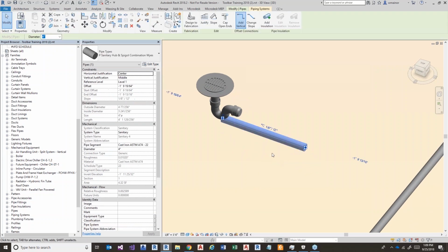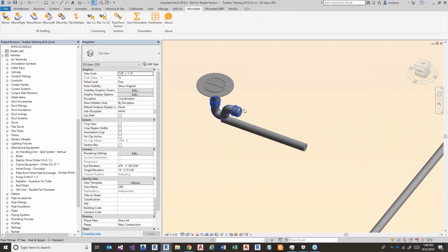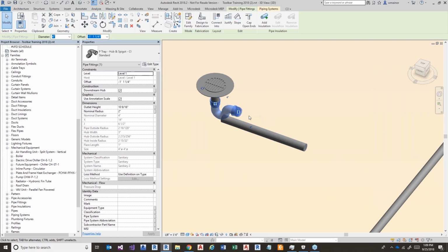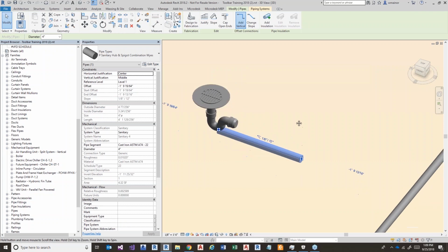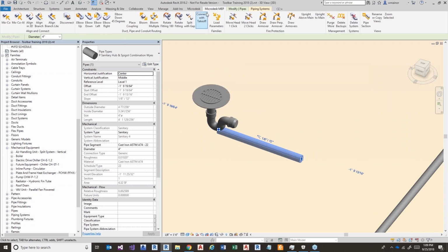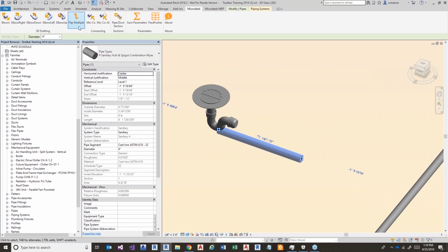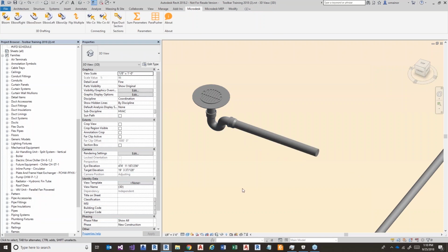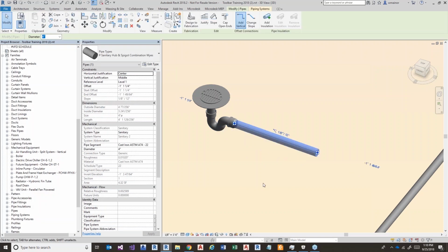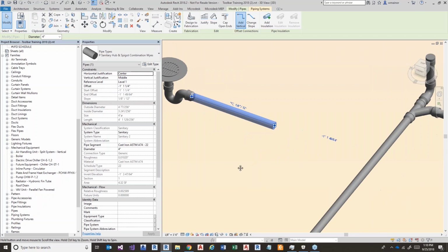And now, I wouldn't want to use the move, connect, align on the P-trap because this connection doesn't have a slope associated to it. But my branch line does. So we've got another command that's abbreviated as MOCO, and that simply stands for move and connect. It does the same thing as the last command does, but without that align function, so that I can preserve the slope, in this case 1/8 of an inch equals a foot.